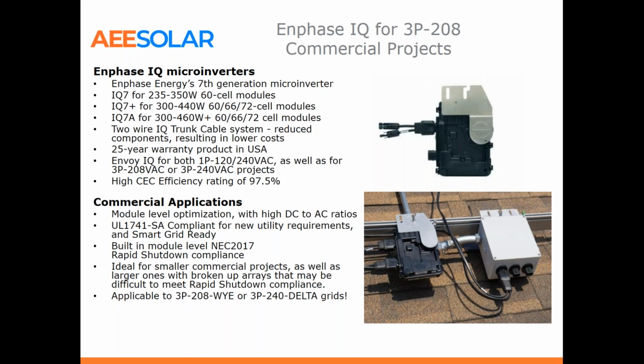And they're especially better for smaller projects, or projects where, as we've had a couple of times, they're afraid of theft of the modules or vandalism. And the choice was either to put a commercial inverter inside and have to do some crazy stuff, or just go with microinverters for carports and gas stations. So Enphase worked pretty well for that application.